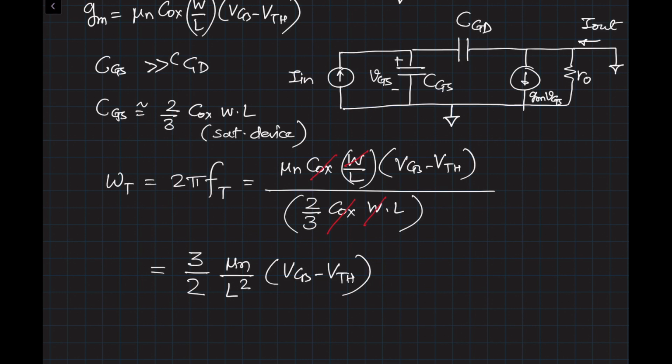So from 5 micron technology in 1989 to now, we are in the nanometer range. Our recent chip was 65 nanometer. The next chip we are going to work on is 40 nanometer or 28 nanometer or 20 nanometer technology. When I talk about these numbers, I'm actually talking about the minimum channel length of the device.